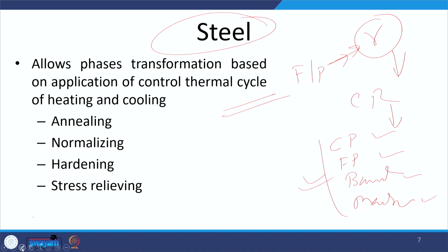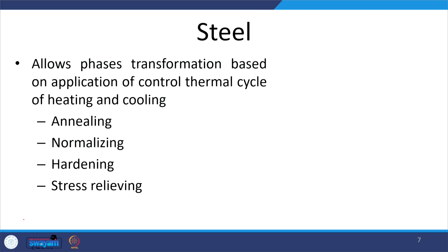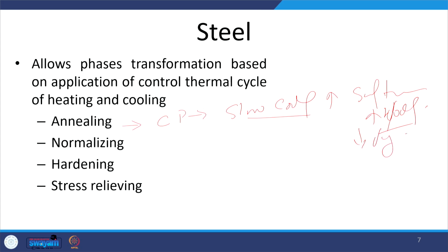So, once the steel is heated to the austenitization condition and homogeneous austenite is formed, depending upon the cooling rate, we can get the desired phases. Say coarse pearlite is realized through slow cooling. Okay, during annealing, this helps in eliminating the embrittlement and inducing softness, increasing the ductility, increasing the percentage elongation. But certainly this will be happening at the cost of the yield strength and the hardness.